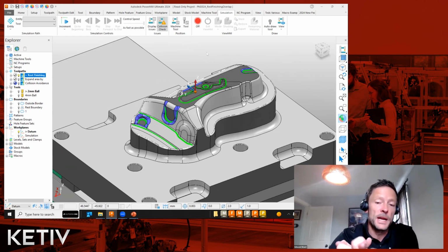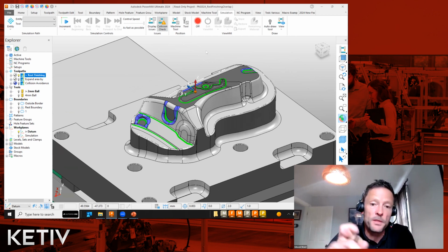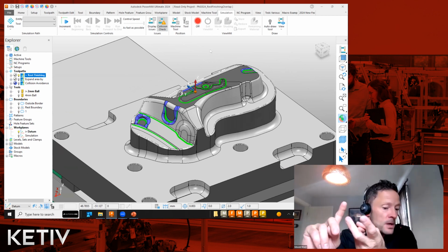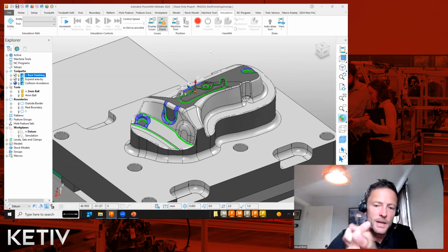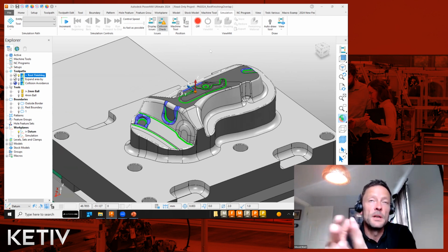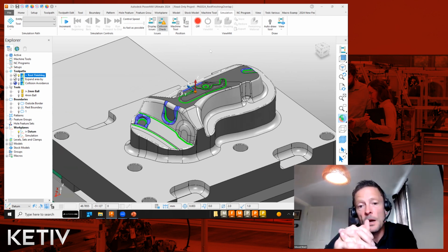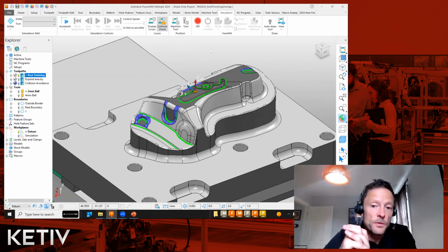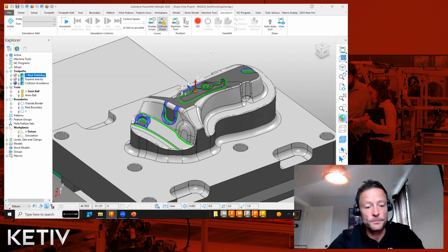That would be a combination of a steep style toolpath and a shallow style toolpath, which could be a choice between a raster style, a lace cutting style, or a 3D offset. But you would always have to go back in and machine those fillets or the small internal corners.